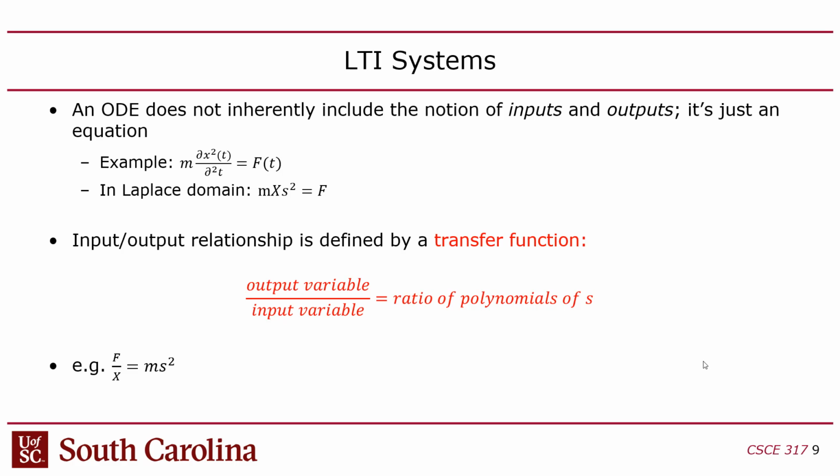So what's on the other side? Well, it turns out, has nothing but s in it. Actually, it's a ratio of two polynomials of s. Does that make sense? So essentially, the transfer function is, at least in a SISO system, all the variables are on one side, and the other side is literally just polynomials of s.